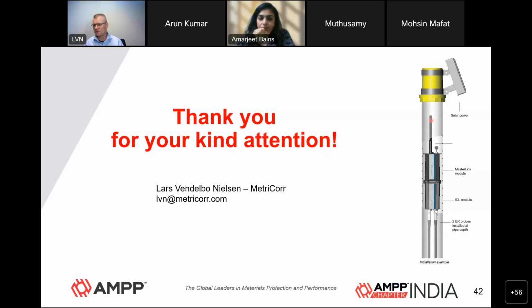You can also use batteries, but again, if you don't want to visit your test station very often, you do need to have a continuous power supply to these data loggers or remote monitors. And today you can have batteries that last, depending on the frequency of your measurements, for 3 to 5 years, and also solar power panels. We have panels that have been functioning well without any problems for 10 years in such a test post.